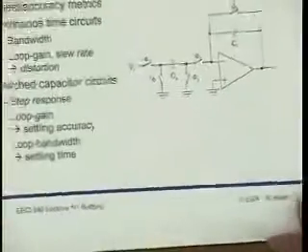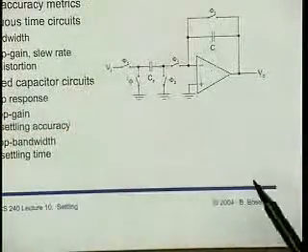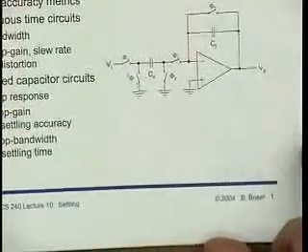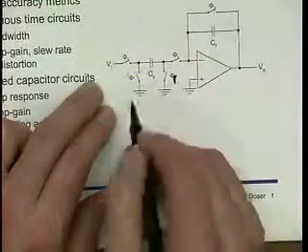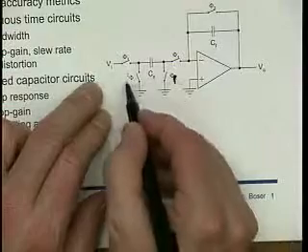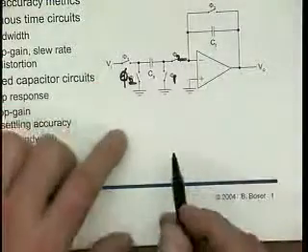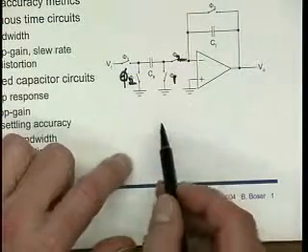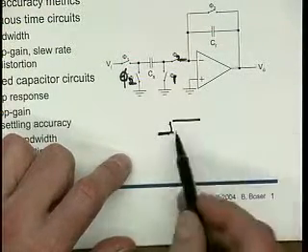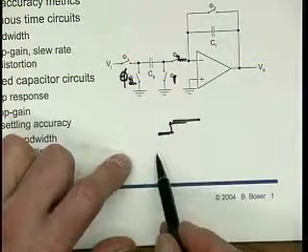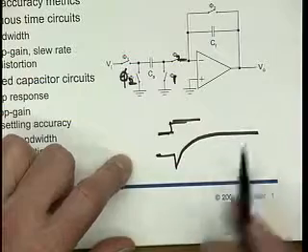Right? And so basically what this circuit does here is that, depending on how we phase it, in particular if we phase it like this, where there's phase 1 and then there is phase 2, then effectively what we are doing to our amplifier is putting in a step, and the output of the amplifier is going to react something like this.